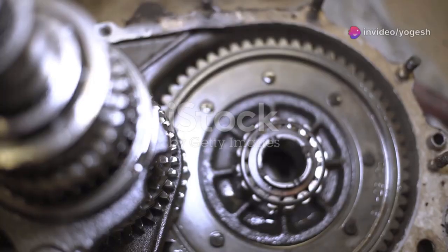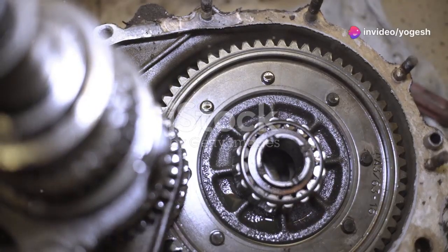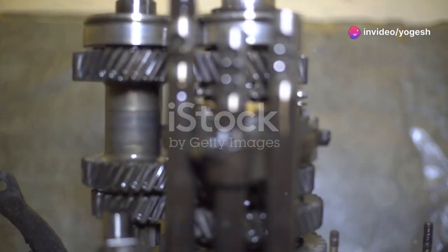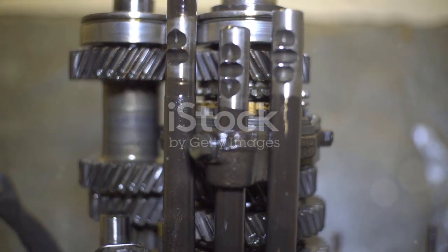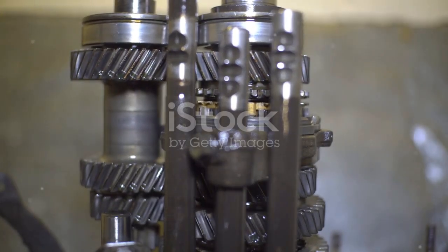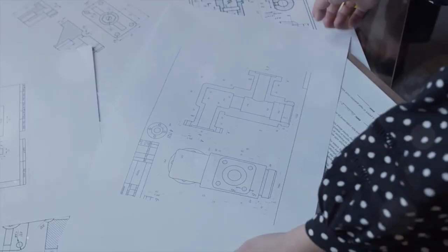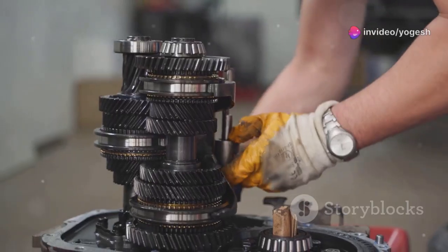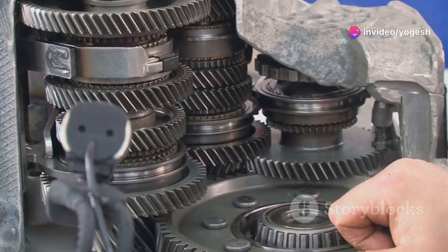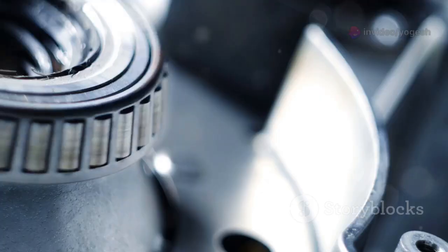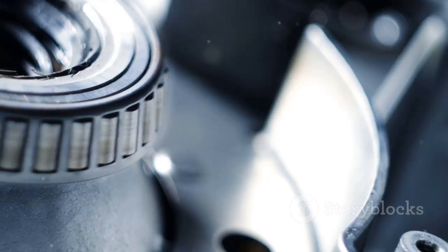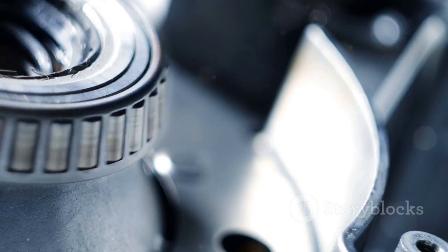Let's see these principles in action with a simple gearbox assembly. The drawing features an exploded isometric view, with each part assigned a balloon number linked to the bill of materials. The assembly sequence is detailed in a stage table. Stage 1. Press oil seals into the housing, with a detail view showing correct orientation. Stage 2. Install bearings onto input and output shafts.